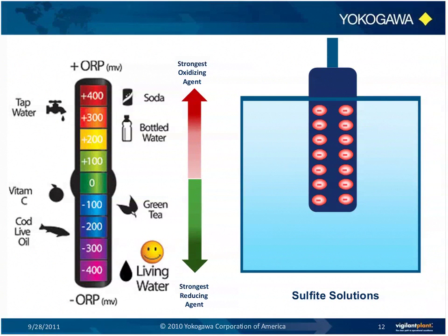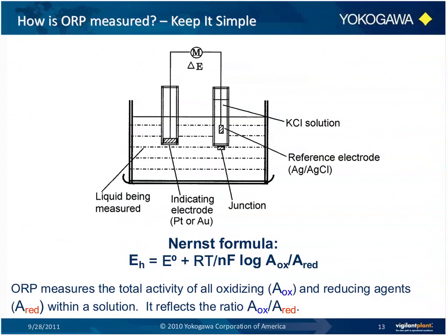Just like pH, ORP is based on the known Nernst equation to determine the equilibrium reduction potential of an installation that contains a conductive electrode and a surrounding conductive electrolyte within a process solution. When a chemically inert noble metal electrode is placed into a solution where an oxidation reduction reaction is taking place, the electrical potential appears at that measuring electrode on that noble metal part, and this potential is called the oxidation reduction potential.